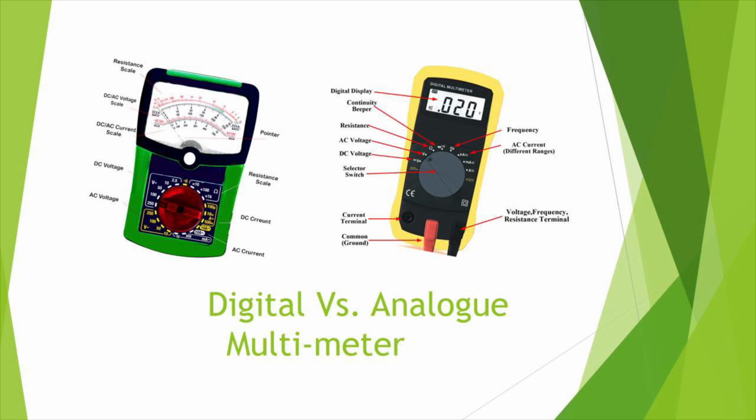An analog multimeter has a lower input impedance than the digital multimeter, but can take continuous readings of changing voltage or currents. The needle movement is damped, but any signal that changes up to 10 times a second can easily be displayed. They are compact and portable instruments and widely used in electronics. I believe now you know what an analog multimeter is. Now I would like to go over the digital multimeter.